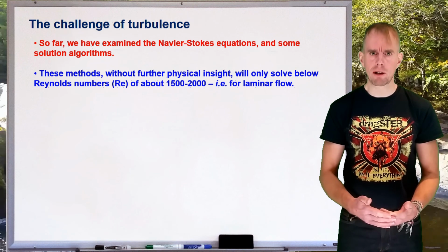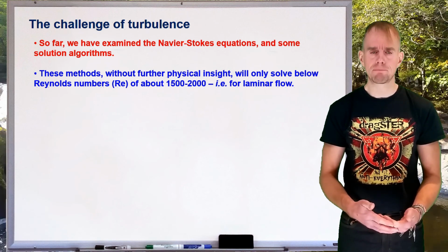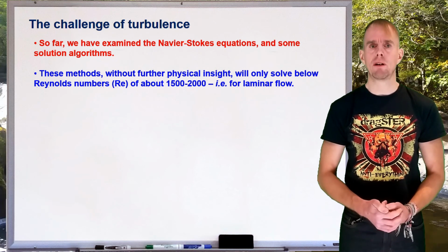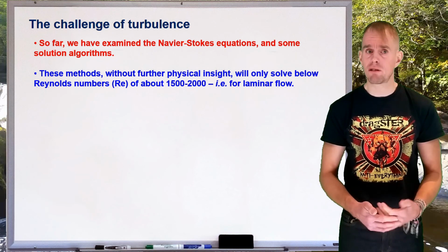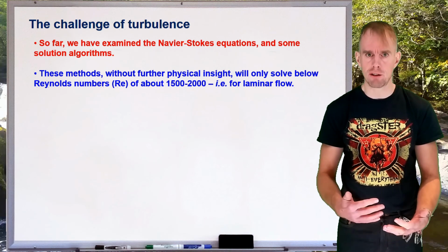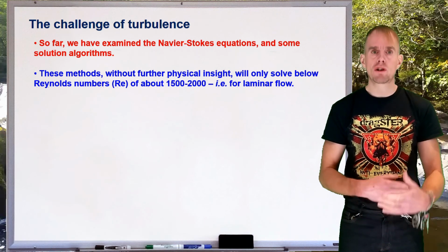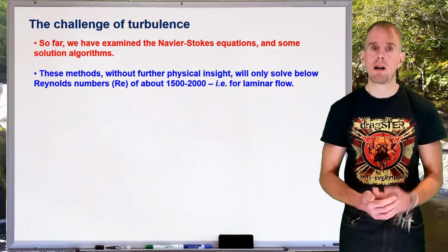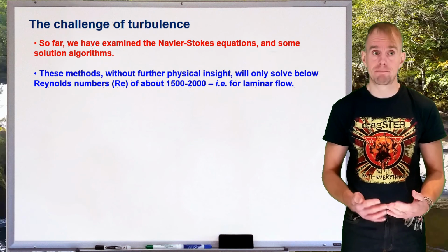You've got creeping flows, where inertia is negligible, very, very low Reynolds numbers. Then you've got inertial laminar flows, where the Reynolds number is significant, maybe order a few hundred, or even high few hundred, 800, 900. When you have inertial laminar flows, you will start to see interesting flow structures form when the flow geometry permits it.